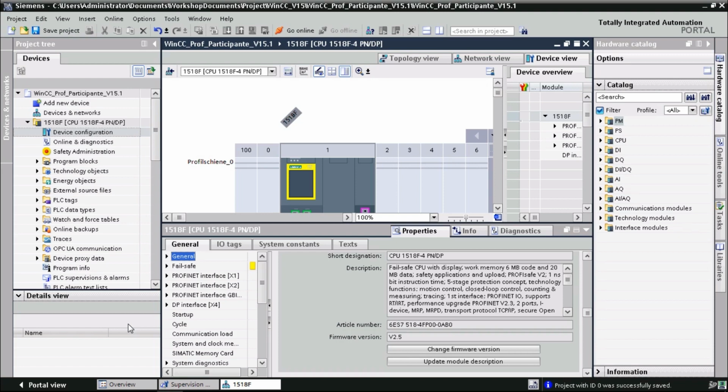Yeah, not much logic in here, so don't expect that much. And the most important thing is here the default supervision FB. We can also create a second supervision FB. When you select function block and you go to language, you can actually see here that we can also choose a ProDiag language, which actually is then just a ProDiag FB.